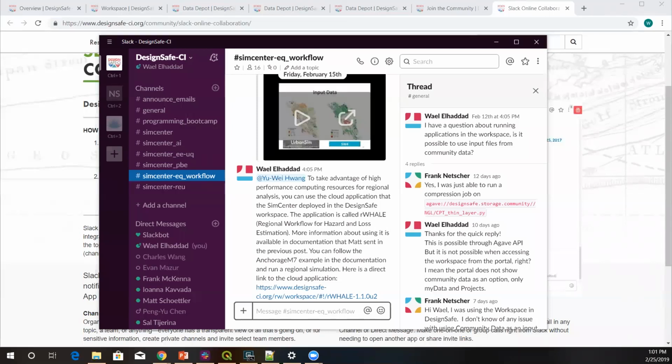The stiffness evaluation and the damping evaluation are actually based on the capacity curves coming from HAZUS. HAZUS can create a capacity curve for any building in a generic form based on basically the height of the building and the area of the building and so on.